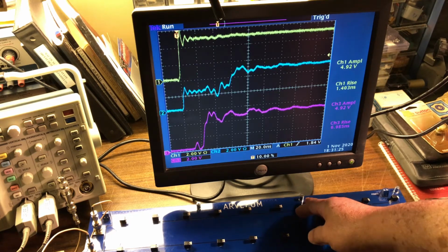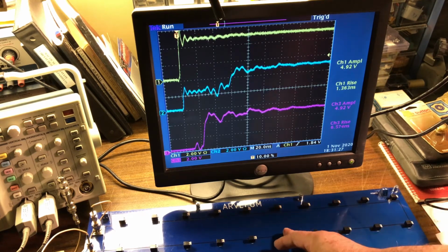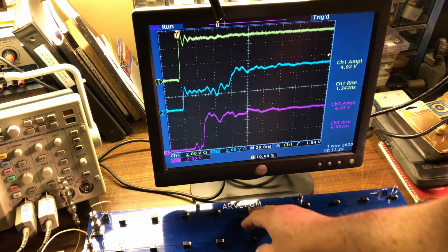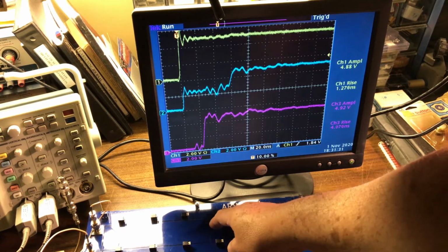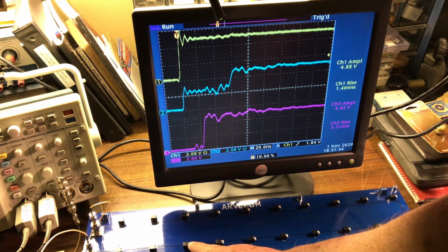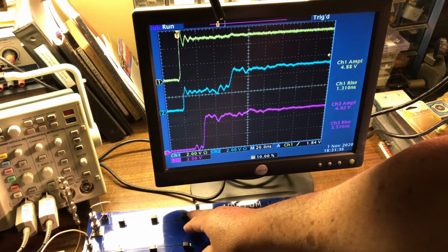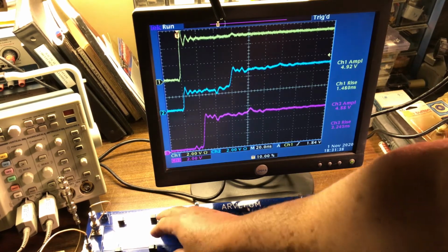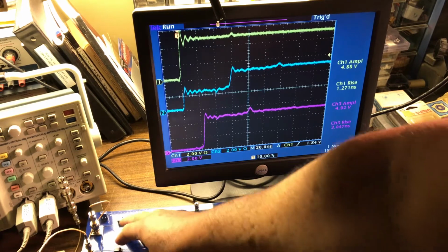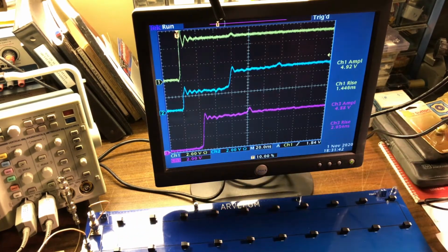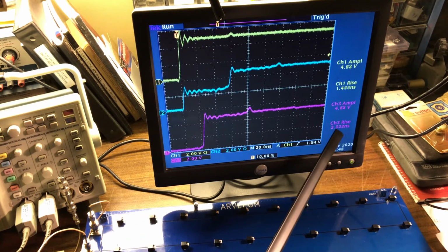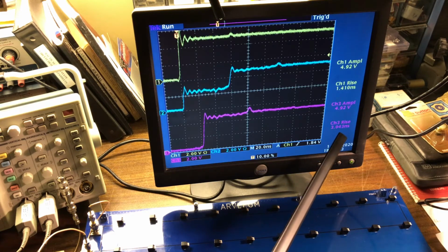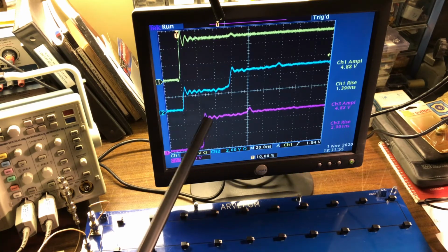See, it's getting better. Getting better. There's not much effect in the middle, but as I approach the edge here, then it gets better, got better, much better, and great. So now you can see that the edge is really fast. Now my edge is at about 3 nanoseconds, 2.7, 2.6 nanoseconds, sometimes 3. But this edge is much faster.